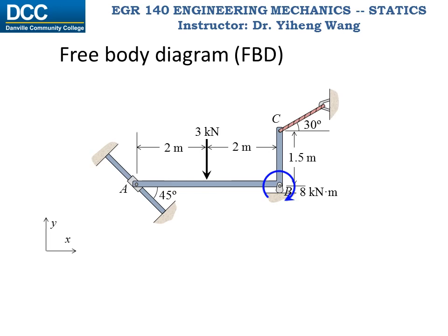First, let's look at the smooth collar at point A. We realize that it does allow movement along the rod, and because the member is pinned to the collar, the member is allowed to rotate either counterclockwise or clockwise. The only motion it prevents is along the direction perpendicular to the rod. Therefore, we can tell the force support is along that direction. It could be either in this direction or in this direction pointing to the right. Let's first assume it is in this direction. This is our first unknown force, Fa, associated with the collar.